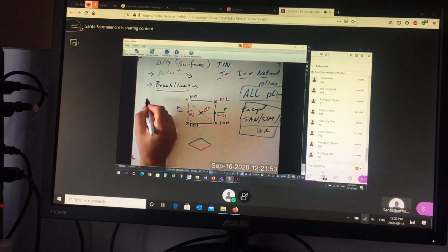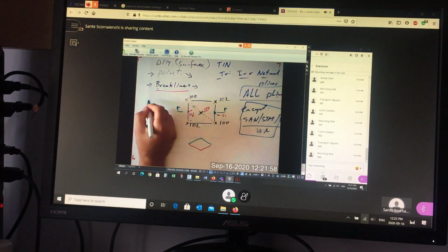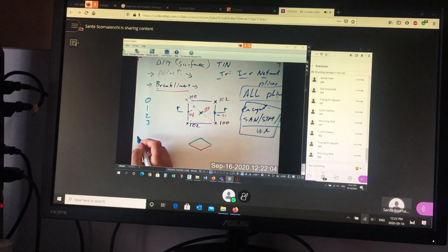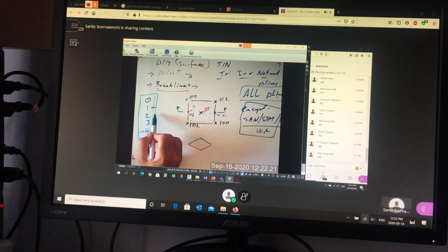Make sure you do PDF 0, we should have done together. Okay, set up drawing. I'll have a topo file by now. Make sure you do 1, 2, and 3, and then put your points 4. Okay, so if you can get all that done, and maybe even import the points when I import the breakpoint, but I will cover that again next week. But this is really the crux of it. Create your description keys, create your styles for points and point labels, create your point groups, and then import your points. If you can have all that ready in your topo file for next class, then we can build the surface and look at the rest of the requirements.